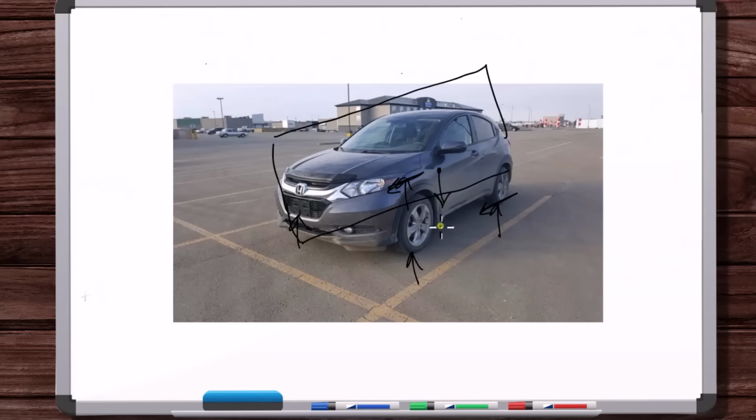Yeah, so it makes sense how, just in general, for a car driving, you can model it with a free body diagram that's planar. Not every time. If the car's turning, then there's more traction on this tire than this tire, let's say. So it's not symmetric then, but just a car driving straight, accelerating straight, or constant velocity straight, whatever, the loads are symmetric. And there's no component of these loads that's perpendicular to that center plane. So you can do a planar free body diagram.